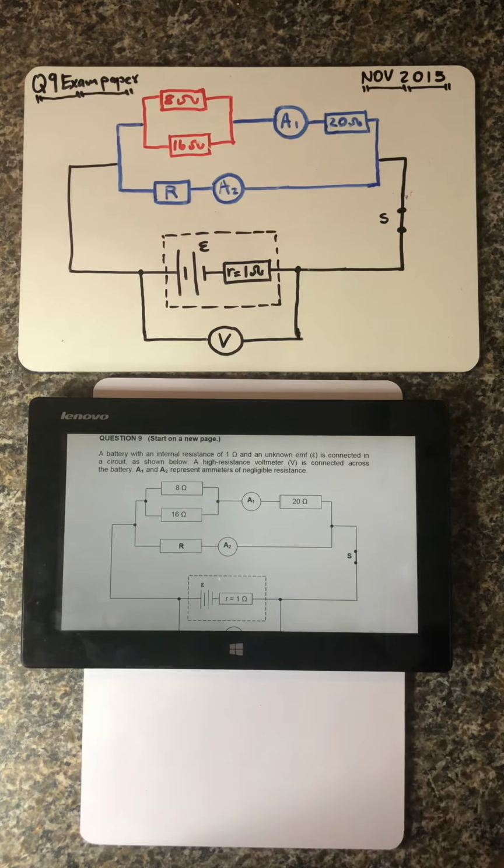So the EMF is the total voltage of those two cells. Okay, that is the EMF. So the moment we've got an EMF and again we've got an internal resistance, then we know not all 3 volts will be used by whatever is connected to that circuit. So you might find that maybe only 2.7 volts will be shared amongst those connections.